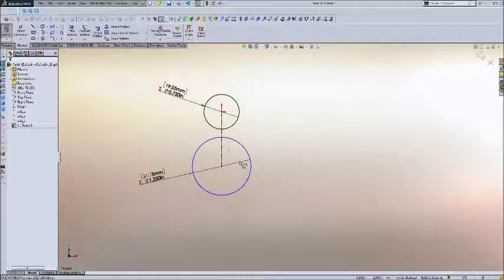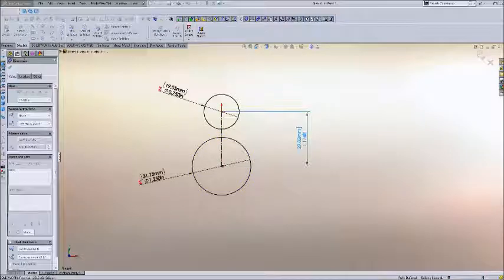The way you find that out is, your center distance is going to be equal to the sum of your two gears' teeth. So this is going to be 13 plus 23. And you're going to divide that by twice the diametrical pitch. So divided by 2 times 20, and that's going to be 40. If you were to use a 32 dp gear, you'd be dividing by 64, sorry. And that's going to be your normal equation. That's going to be your basic center distance. It's the sum of the gears' teeth, divided by twice the diametrical pitch.